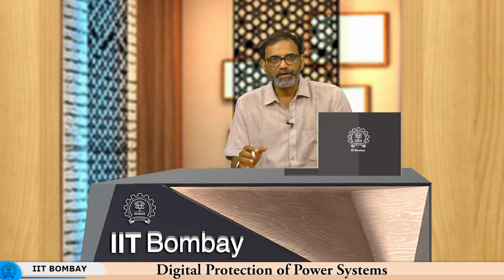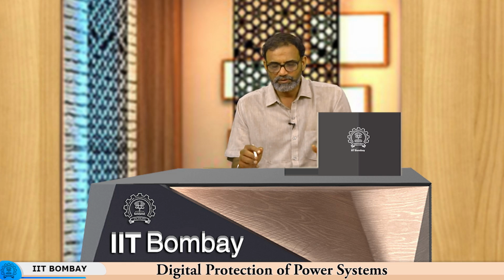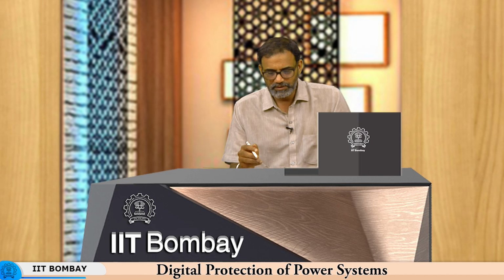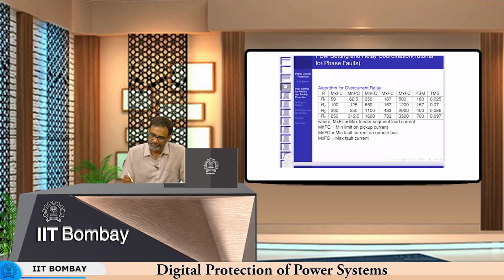The fault currents could vary, as some generators are in, some lines are in and out, and all that. That is why you can get a minimum fault current and a maximum fault current. Or if the load is the same throughout the day and nothing is changing, then minimum and maximum fault current would be the same. So, the fourth column here, the minimum FC, is the minimum fault current on the remote bus.